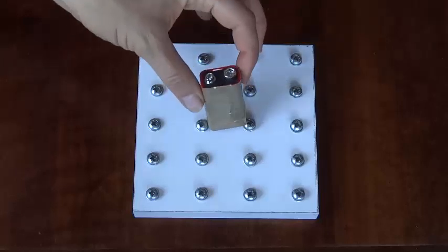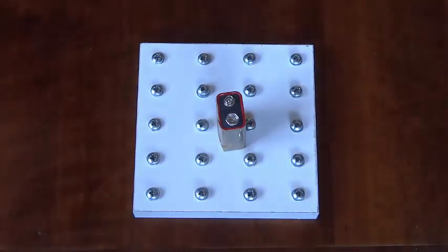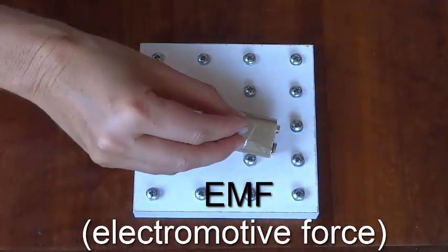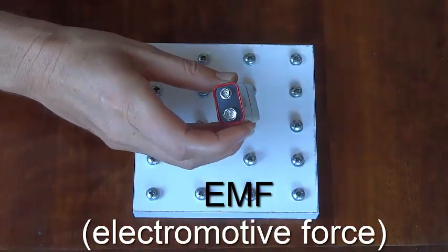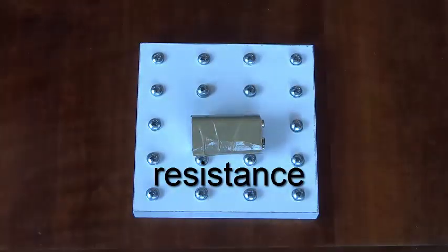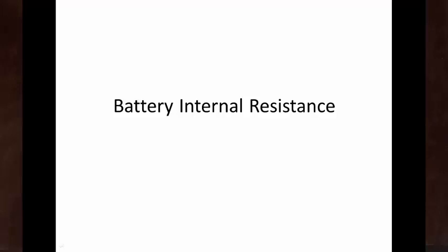A battery like this both provides and removes energy. It provides energy because it has an EMF, electromotive force. There are chemicals inside this battery which undergo a chemical reaction to separate charges from one another so that you get a positive and negative terminal. But inside the battery, there is also resistance, and that removes some energy, making the battery hot. That resistance is called battery internal resistance.